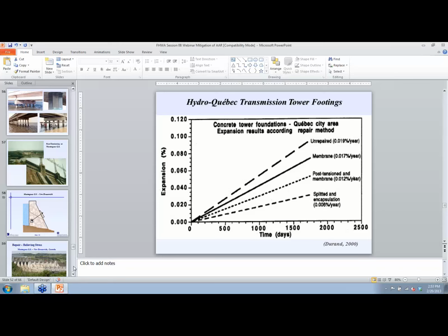I guess the better question, or perhaps a parallel question, is, before considering that, we just need to close the loop on the issue of the buildup of the alkalis at the surface of the steel, the internal sodium and potassium. And I think once that's sorted out, that will determine whether or not the electrochemical approach is viable. And then it all comes down to economics for the owner. The potential benefit, the potential increase in service life relative to the cost of the treatment itself. So we don't really have a definitive answer for you there, but just some general thoughts.